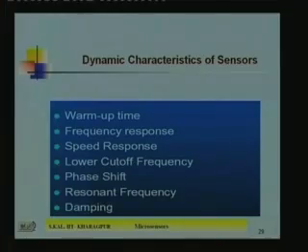Last time, in lecture 2, the microsensor introduction, I was discussing the characteristics of sensor. There are certain parameters which are known as the dynamic characteristics of sensor, namely the warm up time, frequency response, speed response, lower cutoff frequency, phase shift, resonant frequency and damping. So, these parameters also you have to take care of, which are not mentioned in lecture 2.